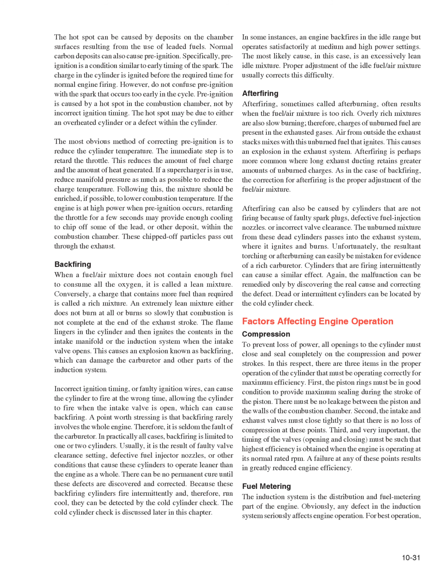A point worth stressing is that backfiring rarely involves the whole engine. Therefore, it is seldom the fault of the carburetor. In practically all cases, backfiring is limited to one or two cylinders. Usually, it is the result of faulty valve clearance setting, defective fuel injector nozzles, or other conditions that cause these cylinders to operate leaner than the engine as a whole. There can be no permanent cure until these defects are discovered and corrected.